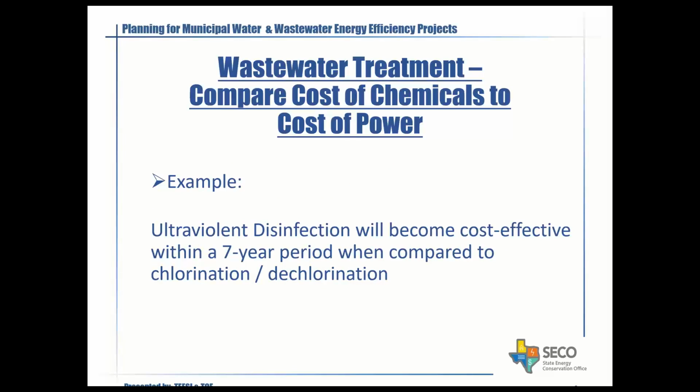One of the other things that we've noticed over the years is ultraviolet disinfection is very cost effective when compared to chlorination, dechlorination. We've found that it can pay for itself in a 7-year period from the cost of chemicals versus the cost of power. So ultraviolet disinfection is not only a good disinfection method, it is a cost-effective disinfection method.